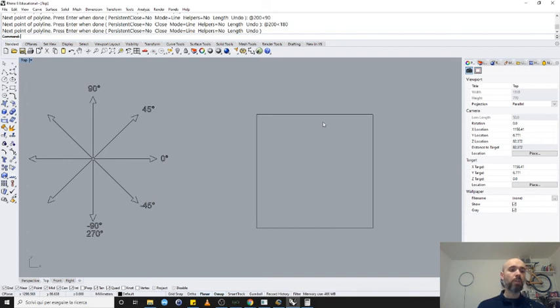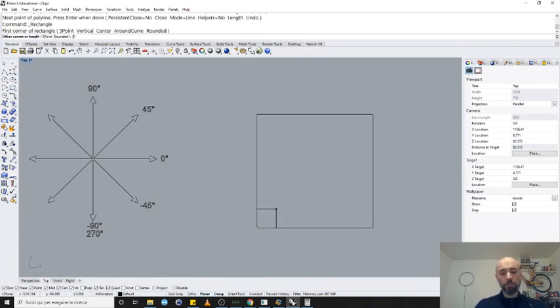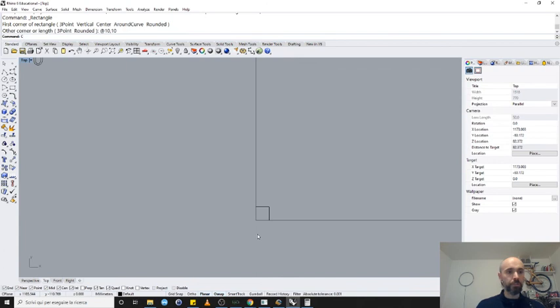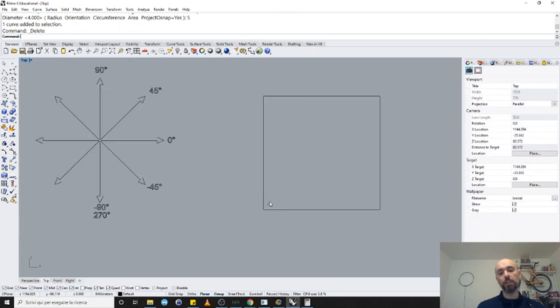What if we want to have a circle in a specific position, that could be 10 millimeters and 10 millimeters, a circle of 4 millimeters? Well, I can draw a temporary square, for instance, relative 10, 10, and have the center point for a circle, let's say of 5 millimeters in diameter. Now when I remove this, I know that the position of this circle is exactly where I want it to be.